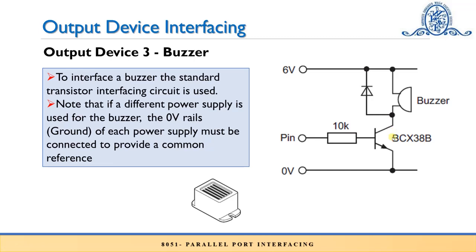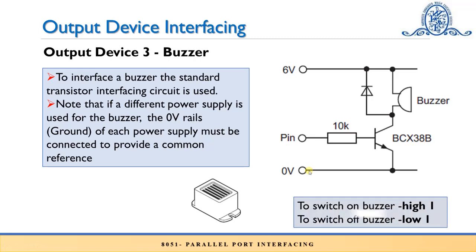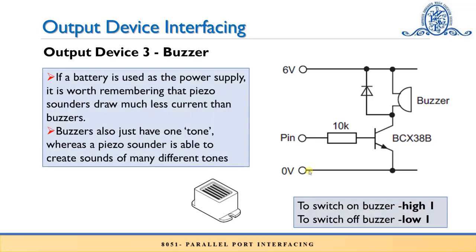Again, in this case, the common point, this 0 volts bus, is to be made common with the microcontroller common point. If a battery is to be used, then a piezoelectric buzzer draws much less current. So you can use a piezoelectric buzzer in place of the normal buzzer.